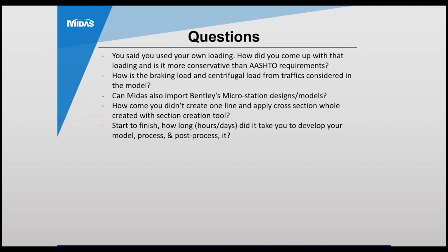Can you please explain how you model the torsional box stiffness? Oh, sure. So for the longitudinal beams, the NCHRP report covers this as well, but essentially what we did is take the entire box section torsional stiffness and divide it by the number of webs in the box. So you're getting essentially half and half for the longitudinal girders. And we verified that with a single box girder element just to see how they compared, and it was quite similar.